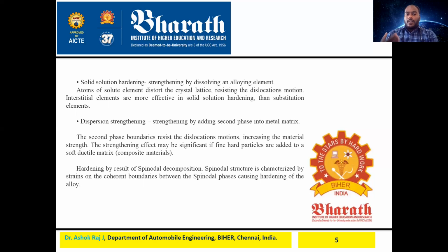Then there is dispersion strengthening, strengthening by adding a second phase into the metal matrix. The second phase boundary resists the dislocation motion, increasing the material strength. The strengthening effect may be significant if fine hard particles are added into a soft ductile matrix, as in composite materials.